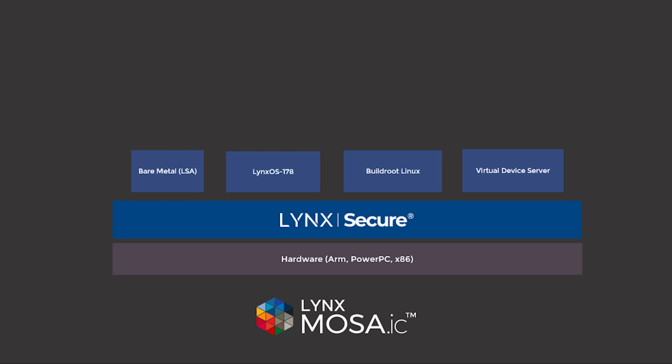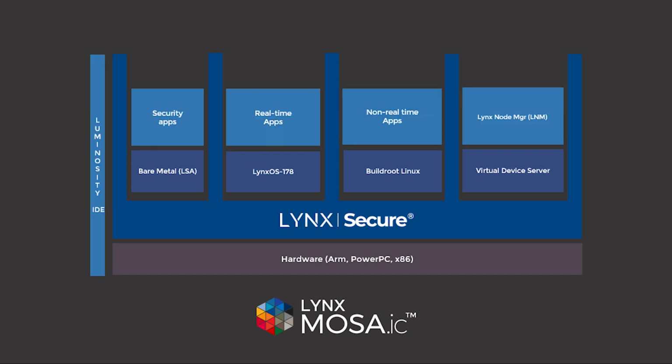We have some people that will only run bare metal code, something we call Lynx Simple Applications, or LSA. Pure bare metal, very small, very deterministic, and basically very high levels of security. We have our own operating system, LYNX MOSA.ic, and that allows you to support DAL-A certification. It has standard APIs like ARINC 653, FACE 3.1 conformance. So your deterministic applications or your software that has to go through safety certification would sit on top of the RTOS.